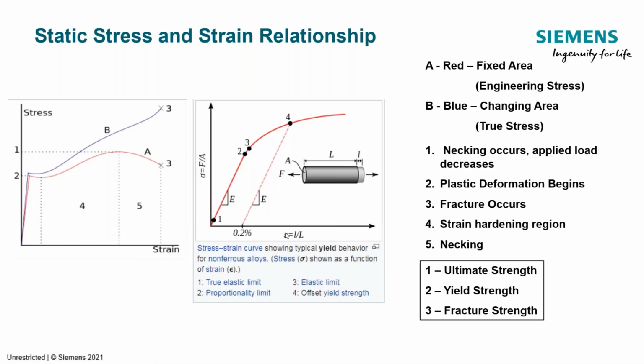Now, one thing just to keep in mind, because we want to give you some qualitative understanding: let's say I don't want to get into a nonlinear stress-strain model. One of them is called Ramberg-Osgood, which we use in fatigue. I'm just going to use Hooke's law. Well, what happens is, for a given strain, if you use Hooke's law, you will over predict the stress. Okay, so keep that in mind. If we go elastic and use Hooke's law, we're going to over predict the stress.